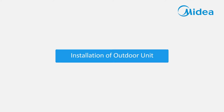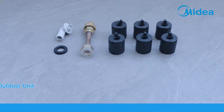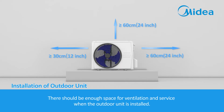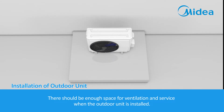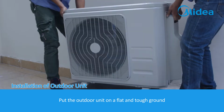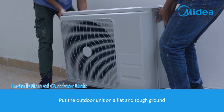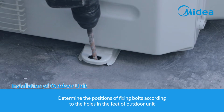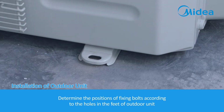Installation of outdoor unit. Check all the accessories of outdoor unit. There should be enough space for ventilation and service when the outdoor unit is installed. Put the outdoor unit on a flat and tough ground. Determine the positions of fixing bolts according to the holes in the feet of outdoor unit.